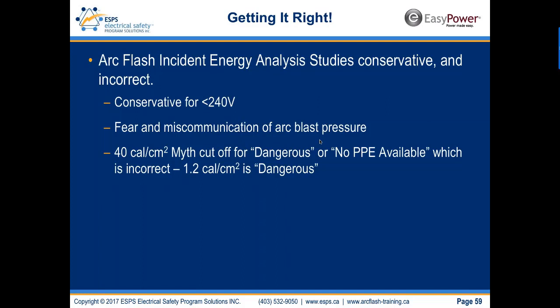There's fear and miscommunication of arc blast pressure in training and facilitated through the studies, where the results say dangerous, there's no PPE available over 40, which in reality there is. There are arc flash suits up to 140 cals. So if you have performed studies, I encourage you not to report 40 calories per centimeter squared or greater as dangerous. You should actually report the actual incident energy calculated to the client, and the client will decide where they cut off work. Do not let the software make that decision for you or for the client.